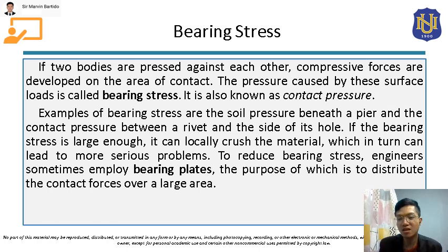This is the most frequent problem that we can encounter in solving for bearing stress. If the bearing stress is large enough, it can locally crush the material, which in turn can lead to more serious problems. To reduce bearing stress, engineers sometimes employ bearing plates, the purpose of which is to distribute the contact forces over a larger area.